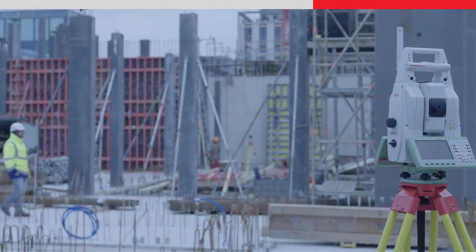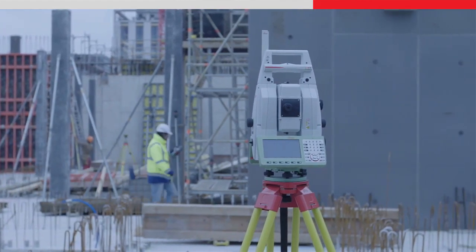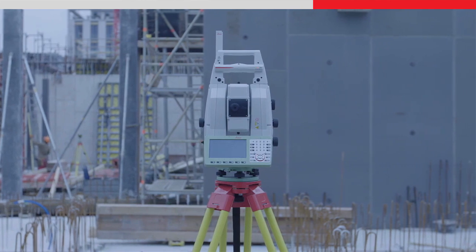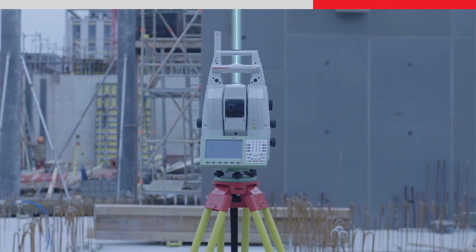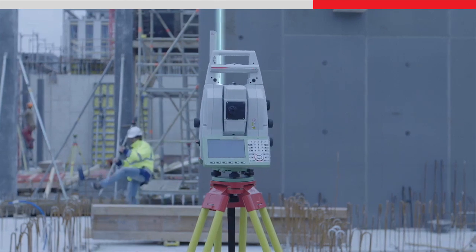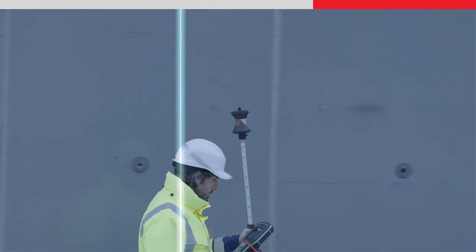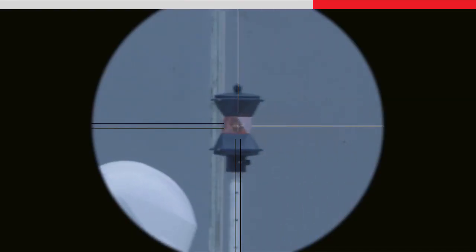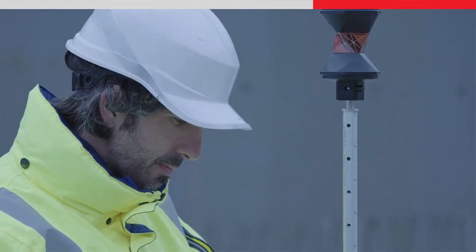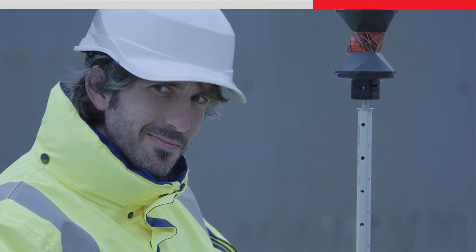Imagine during measuring points, the target disappears from view behind a wall and the instrument loses lock. After the target prediction, a cube search will automatically begin. The multistation will turn back 45 degrees from where the target was lost. As it turns back, the vertical fan will cross the target and then lock to it. Time is saved as there is no need to stand still and wait for the instrument to find the target again.